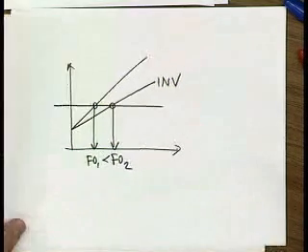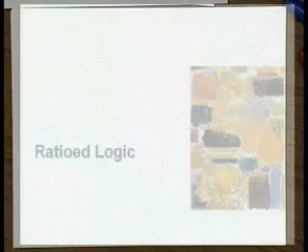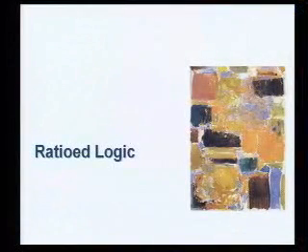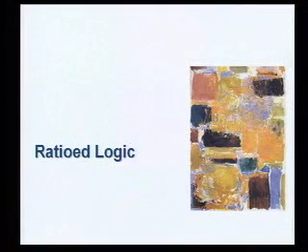Okay. So now let's get to the fun part of the course, and let's analyze a couple more logic families. So we learned in standard complementary CMOS that for the implementation of a function, we really need to implement the function twice. We have to have the pull-down network, we have to have the pull-up network that implements the same function but just covers different values, logic ones.